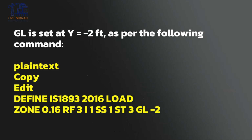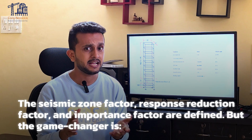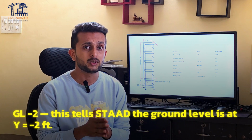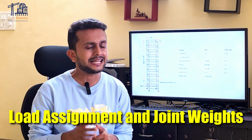The syntax will appear over here. The seismic zone factor, response reduction factor and importance factor are defined, but the game changer is GL. GL minus 2 tells that the ground level is at y minus 2 feet. Now in the next phase, you just have to go with the load assignment and joint weight.